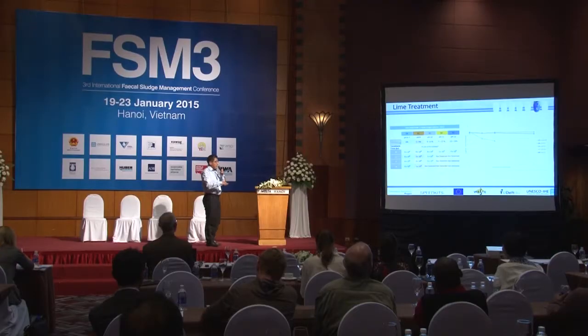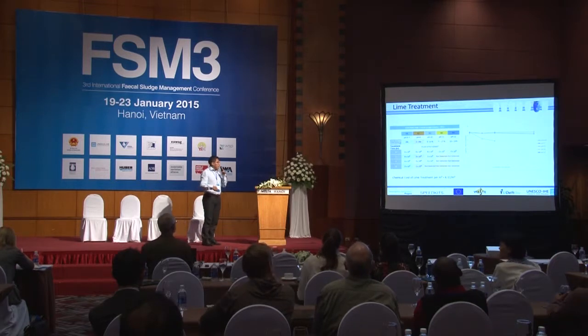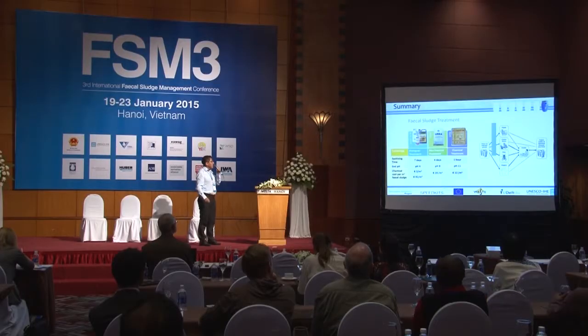The reactor, which was under pH 10, after 5 hours was free of pathogens. About the costs, based on local cost in Malawi, to treat 1 cubic meter of fecal sludge, it's approximately 12 euros.